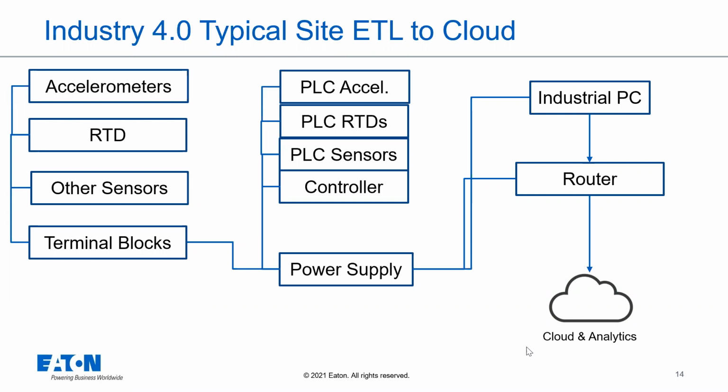They could route it to the cloud, and it's pretty much the same way. The PLC, essentially connected to the PLC or the RTU, then goes to the industrial PC, which could be using anything from OPC UA, Modbus TCP, in some cases maybe even Modbus RTU. It just depends.